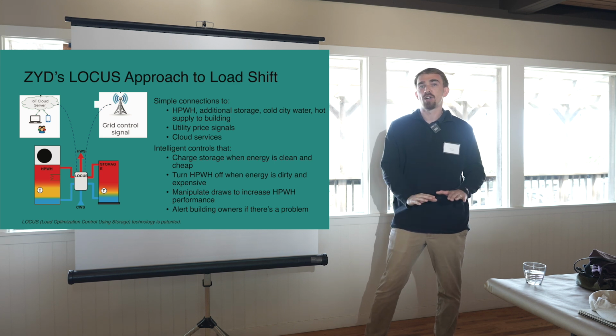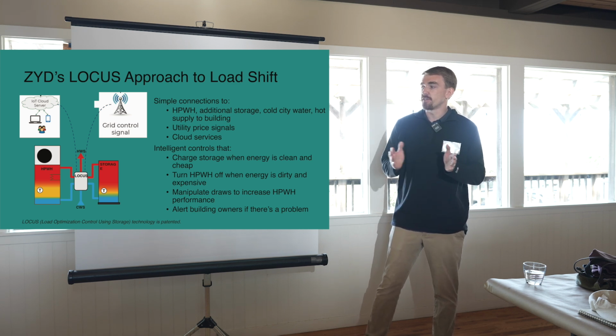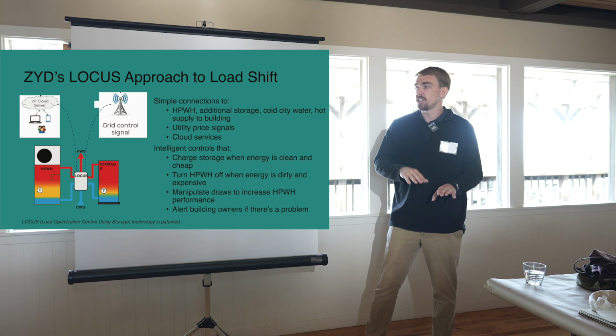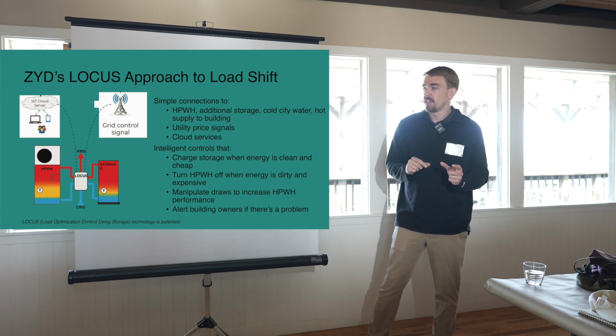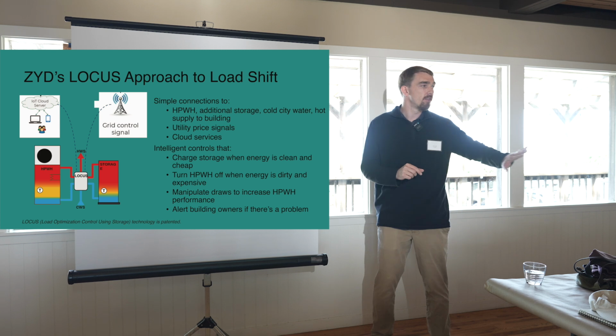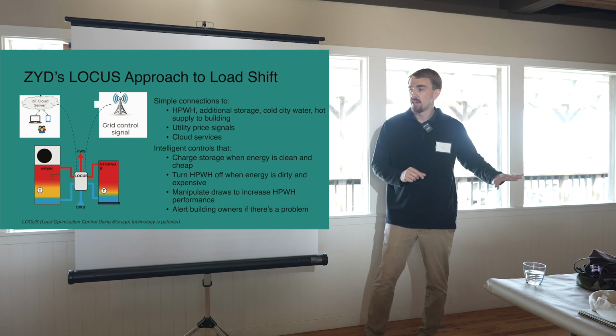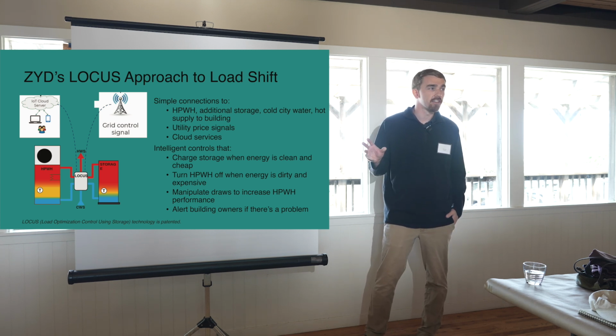When the price signals are lowest, based on their forecasting, they're going to charge this storage tank up, and then when the price signals are high, they're going to isolate the heat pump, not draw from the heat pump at all, and they're just going to let the storage tank handle that load.